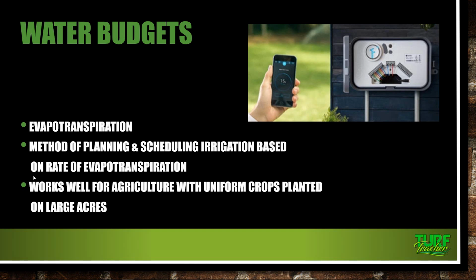I'll also put up a worksheet, a water budget tool quick start guide, from the EPA WaterSense landscaping, but we get that ETo from their website. Basically our monthly baseline is the amount of water a typical landscape would use during its peak watering month. And so we will measure our landscape in square feet.